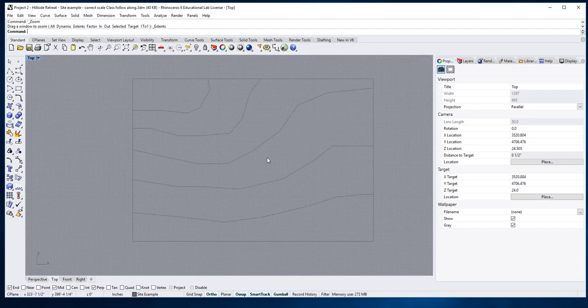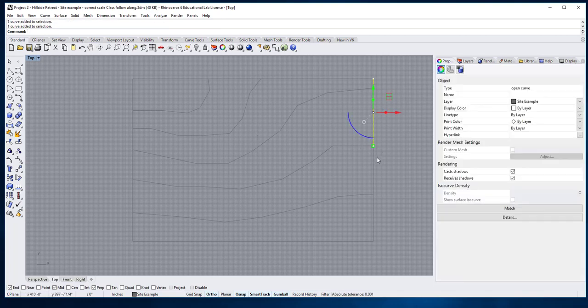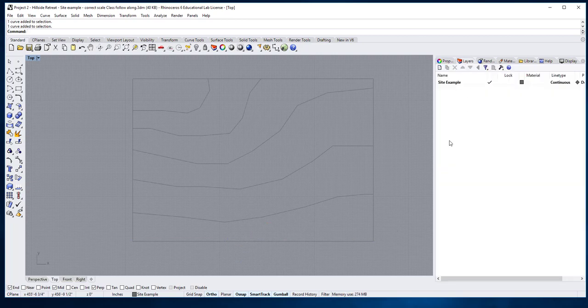Zoom to your extents as best as you can. The first thing we want to do is make sure that all these lines are separate now, so we want to join them together. If you remember, you highlight the pieces and you have to use shift in Rhino. We just made a switch from AutoCAD to Rhino, so we may fumble a little bit with the commands.